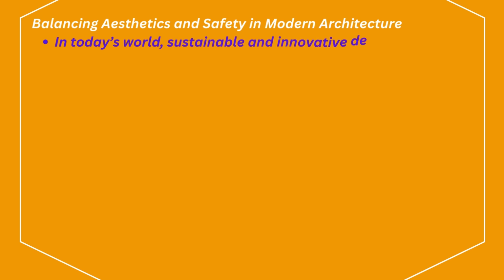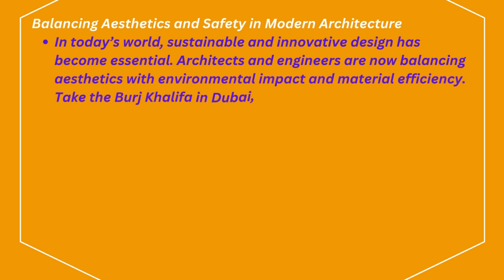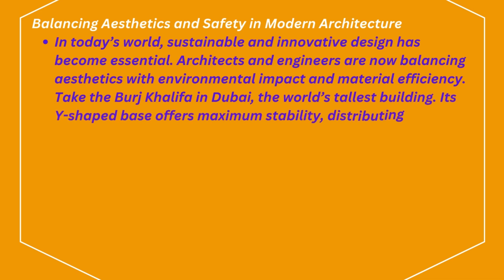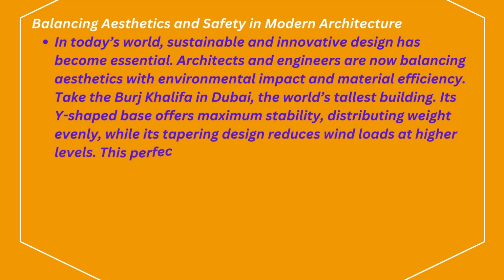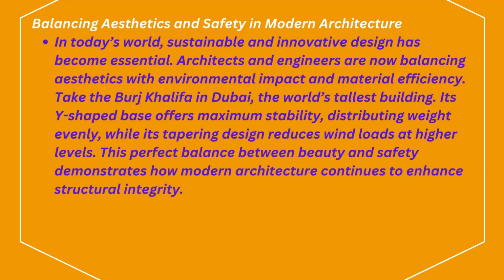Balancing aesthetics and safety in modern architecture. In today's world, sustainable and innovative design has become essential. Architects and engineers are now balancing aesthetics with environmental impact and material efficiency. Take the Burj Khalifa in Dubai, the world's tallest building. Its Y-shaped base offers maximum stability, distributing weight evenly, while its tapering design reduces wind loads at higher levels. This perfect balance between beauty and safety demonstrates how modern architecture continues to enhance structural integrity.